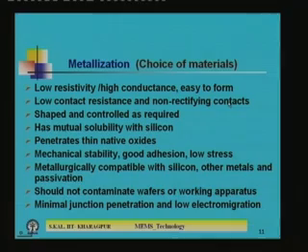Other is the low contact resistance, because in VLSI or even in MEMS devices the contact windows are very small, and in some cases you go for, say, even 5 micron by 5 micron contact, in some cases 10 micrometer by 10 micrometer contact. If you go for ULSI devices, the contact windows are getting much more smaller. So, in that case, it will introduce some contact resistance, and that contact resistance should be as small as possible, otherwise additional parasitic resistance comes into the circuit. So, that you have to shape and control as required.